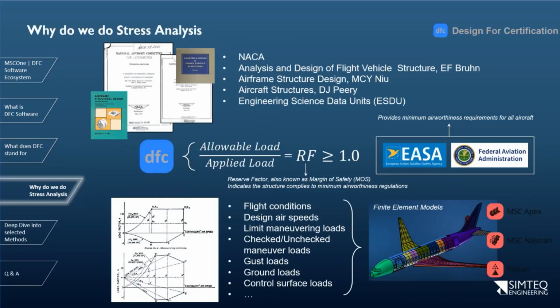Maybe just looking into the analysis methods and calculations to evaluate the structural design. We've covered this in the previous sessions as well, but just briefly, DFC software bridges the gap between the approved methods that are recognized by certification authorities and the results generated by FEA models. So in order for us to get to an RF value, or a reserve factor, we need to compare an allowable load with an applied load.